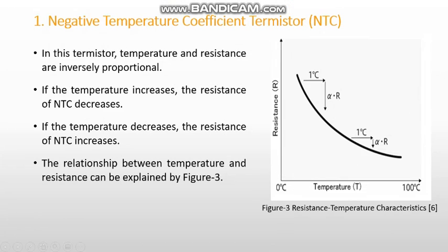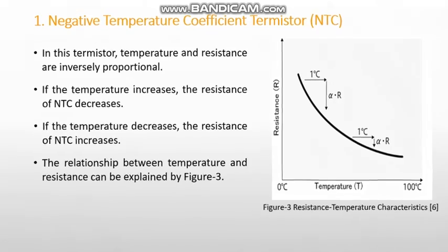In this thermistor, temperature and resistance are inversely proportional. It can be seen in Figure 3, resistance temperature characteristic. If the temperature increases, the resistance of NTC decreases. And also, conversely, if the temperature decreases, the resistance of the NTC increases.